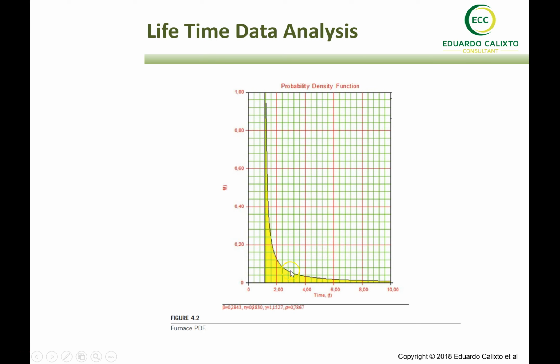The furnace is expected to have a Gumbel PDF, which means a very low chance of failures in the beginning, with failures starting after 10 years and the failure rate increasing. Unfortunately that is not what happened, but we can learn from it, and during our run analysis we can input this information in the model to demonstrate that if we do not change the product that we input in this plant, or even, which is the hardest modification, try to modify the internal structure of the furnace, we will have low performance caused by this degradation.